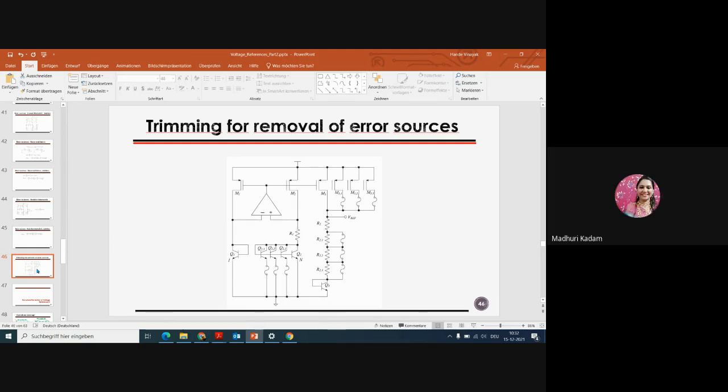So standalone means suppose there is only one IC of band gap reference only. That's what I'm talking about. When we say SOC, there are multiple circuits on one chip. There may be a band gap reference, an op amp, an A to D converter, a low noise operational amplifier, low noise chopping circuits, after that a data converter, after it some digital processing DSP part or something like that. So there we can't go for trimming. This is only useful for the standalone IC of band gap reference. According to my analogy, yeah, it is true. Okay, thanks.